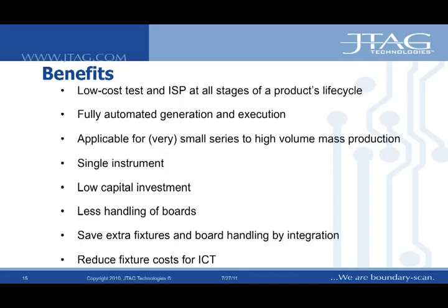R&D, manufacturing and field service all benefit from using this technology. It makes test and measurement and in-system programming on modern very fine pitch boards possible at low cost and at all stages of a product's life cycle. A single instrument that provides the interface between the JTAG port on the target board and the PC can control the various applications we have seen before, as well as future applications, resulting in low-cost capital investments.